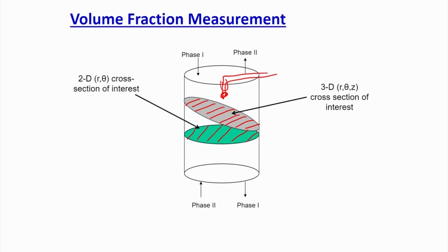So, that is my interest. I want to find the epsilon volume fraction with position and with time, both across the cross section as well as across the volume if possible. That can be done with tomography, because you are going to scan the whole column and cut the information into slices. You will get pixel-wise how the volume fraction is increasing or decreasing. Each pixel gives you information, and that is the major advantage of this technique.